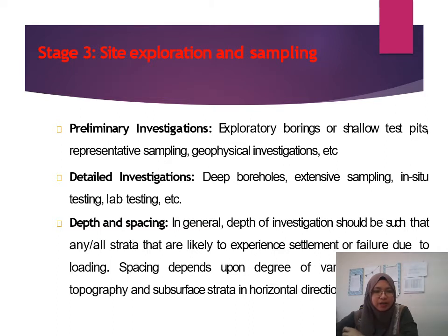spacing. In general, the depth of investigation should be such that any strata that are likely to experience settlement or failure due to loading are covered. Due to the site investigation, there is a guideline. There is a guideline on the depth and spacing of your boreholes. For example, if you design for a critical structure, such as a hospital, the depth and spacing of the boreholes should be more, because the construction is very important, it's very critical.